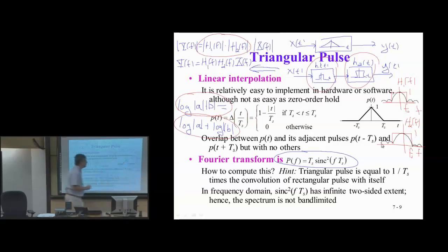Okay. Now, if I multiply the two magnitude responses here that I've shaded in black, the null bandwidth hasn't changed. Pass band is still the pass band, the stop band is still the stop band. 1 multiplied by 1 is still 1, so my pass band is still 1 in linear units and 0 in dB. But the nice thing about this particular filter is the stop band attenuation has increased to 27 dB. Still not a great filter. We've designed filters with 40 dB, the demos with 60, 80, 100. So 27 isn't a lot, but it's better than 13.5.